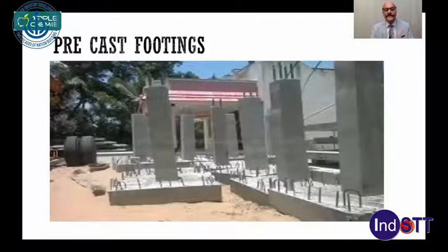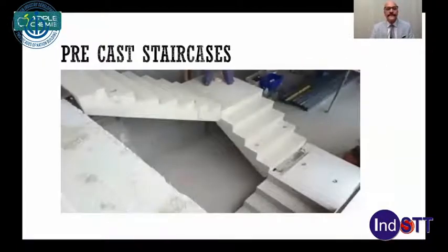Wherever these connections are avoided, especially in smaller buildings, what is mostly useful is footing plus column. So you have a stub column and a footing, everything put together. It can be cast together, and then you shift it to the side, and that gives a benefit.